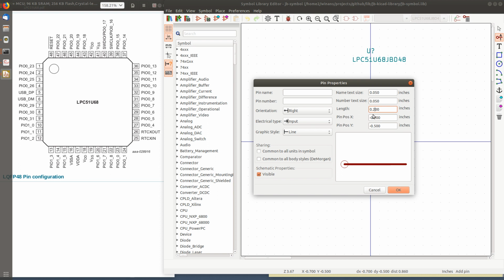It should be a multiple of 0.05 inches, otherwise the snap to grid in the schematic editor will upset most people. So 0.2 is pretty reasonable. That's what, like I said, most of them use. All right, so then you just go around the horn and create your pins. The pins can be placed with the terminal bulb, this little bubble, on the left or the right. I don't know why they chose these names. I guess right to them means that the chip body, the picture, the description of the pin will be on the right. And they can go up and down like so. And what I'm going to do is draw this chip the same way you see it here. So I'm going to have pins that go out this way and down and over this way and up like that and so on as they go around.